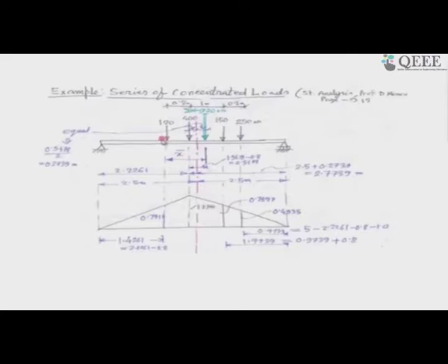You have the distance between the loads known. A little bit of computation onto the figure will be very good for you. You have already computed in the formulation that x is equal to x dash by 2. So, this geometry, this is the center line, where 250, so total is 5 meters. So, it is 2.5 meters and 2.5 meters here.